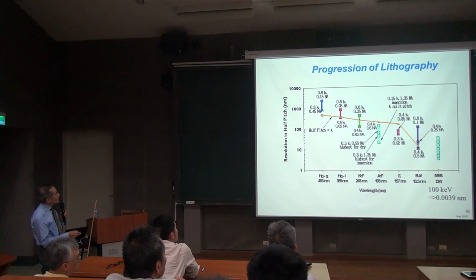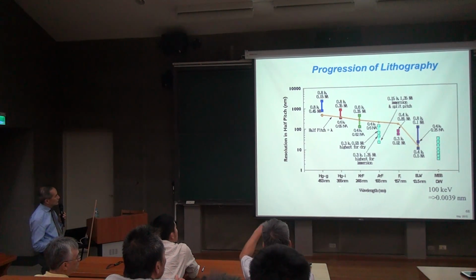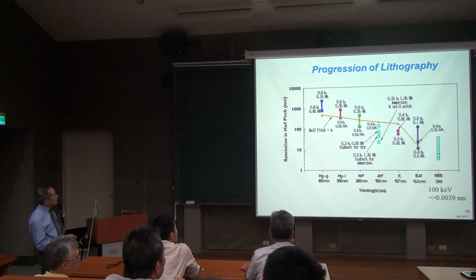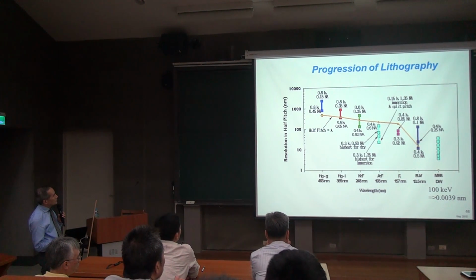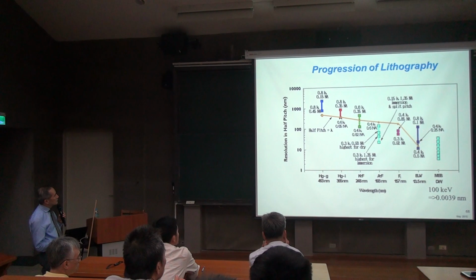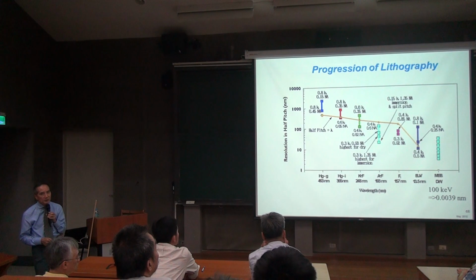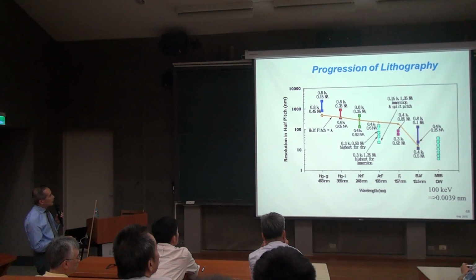Then we're saying it's very tough to increase this NA. So we reduce the wavelength to 365, and we reduce the NA, still at the same 0.8 K1. And now we push this NA to 0.65, and also we have to pick up some K1, 0.8 to 0.6. We're already dealing with this here. That is about 300 nanometer, isn't it? It's already below wavelength. Okay, 365 is my wavelength. This is only 300.